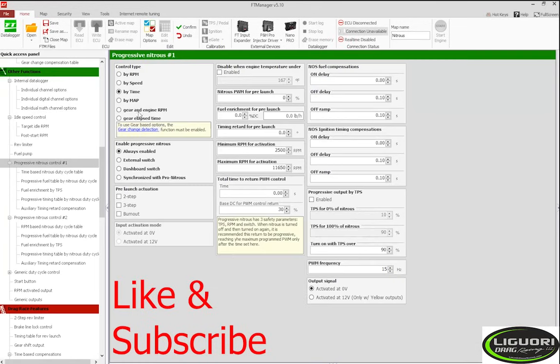So that's by time, and we can enable the progressive nitrous by always enabled, external switch, a dashboard switch, or synchronized with Pro Nitrous. So I personally always, since it's a nitrous bike and I run nitrous all the time, I have it always enabled.